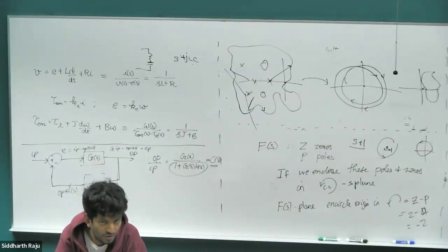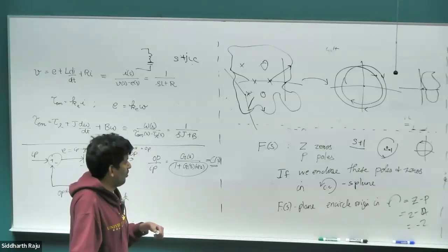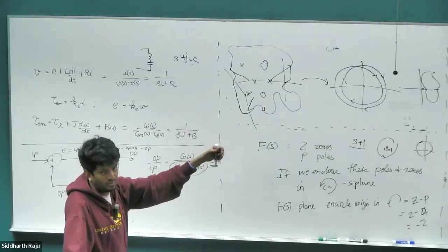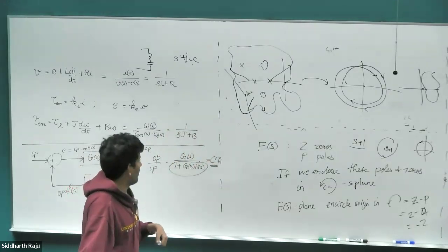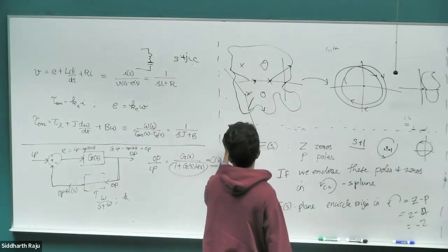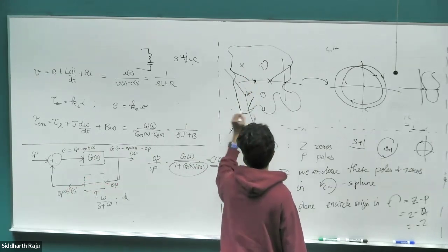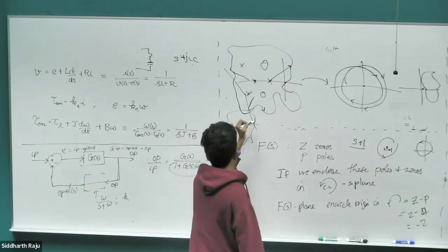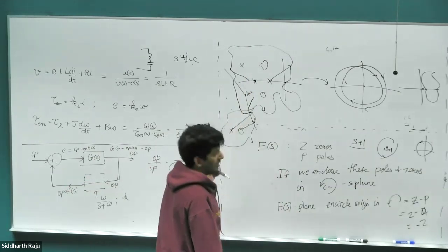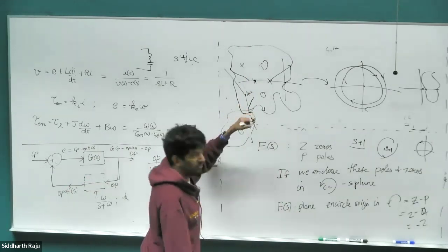If we have the same number of poles and zeros, then we don't circle the origin at all, right? Yep, we don't. But do we know where exactly the circle will be placed? It depends on what you choose your loop to be. Because depending on whichever loop you choose, the way the circle comes out on the other side will change. It's basically the net distance. So if you had, let's say, a pole and a 0, and you had some kind of encirclement, whatever vector angle is being given by this is going to get somewhat cancelled out by whatever angle this is giving at that point, right?